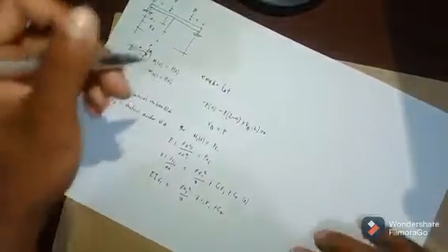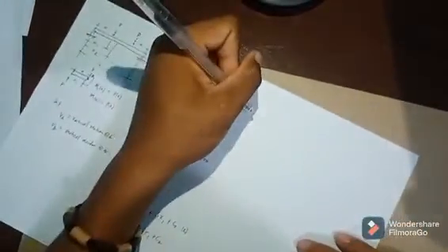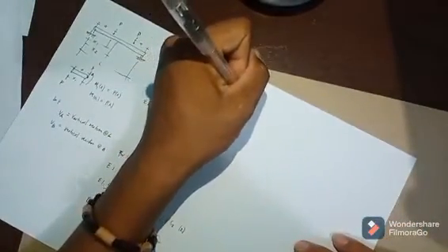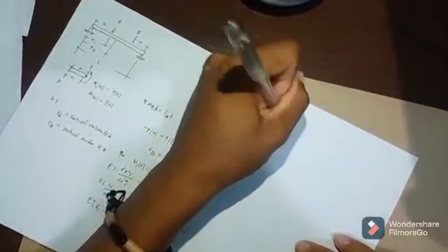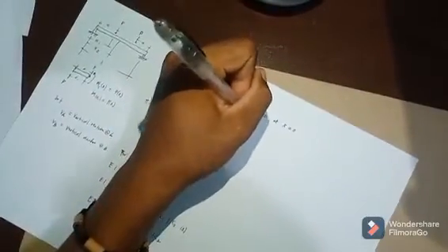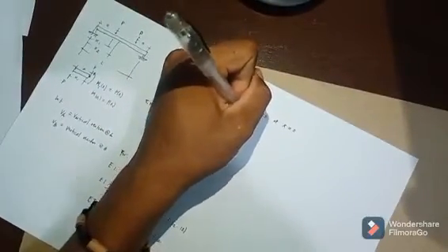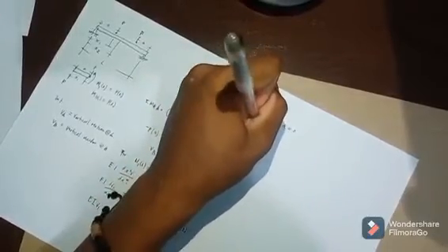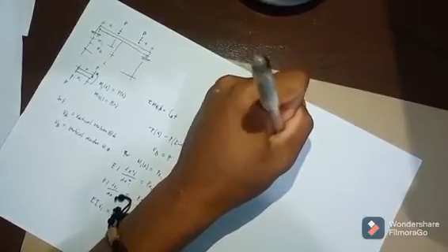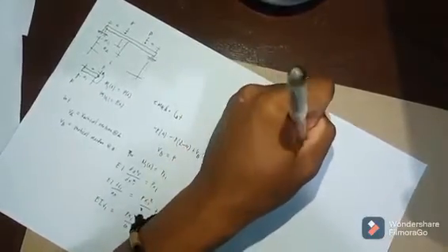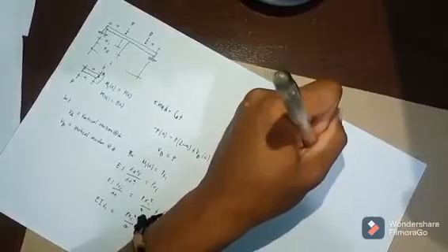So for the boundary condition, we have v is equal to 0 at x is equal to 0. So EIv is equal to P x sub 1 cubed divided by 6 plus C1 x sub 1 plus C2.